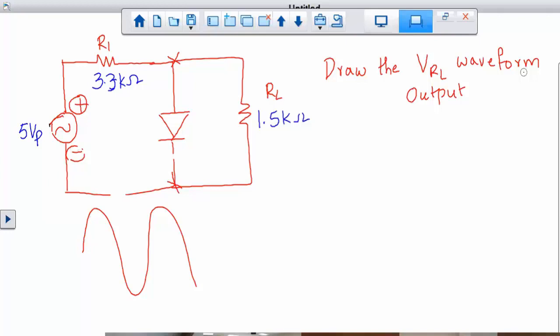Does that make sense? So if R1 is on the bottom there, it would then be a negative flip? No. Don't change the orientation of components. The R1 should be right there. But even if you put it at the bottom, for that matter, it's still going to be a positive clipper. Just for the sake of discussion, if you throw R1 right here, it's still a positive clipper. Which side is being clipped is decided by the diode, not by R1. But the diode would be in reverse at that point, because of R1, reverse-biased diode, load.